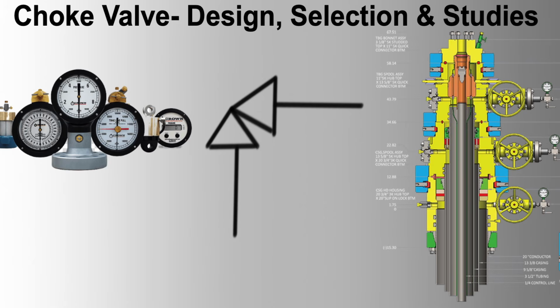2. Preventive maintenance. Cleaning. Regularly clean the valve to remove debris and prevent clogging. Component replacement. Replace worn or damaged components such as seals and actuators to maintain reliability. Practical examples of issues and solutions. 1. Issue: instability in upstream pressure control.